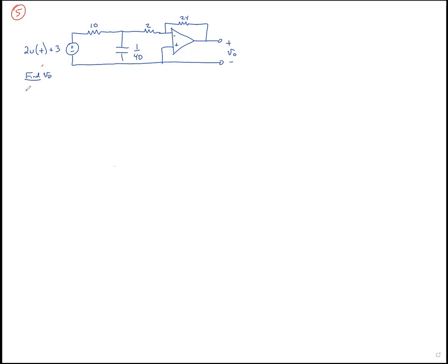So your first step, predictably, is the same as your first step in any first order circuit. Take a look at it and see if it indeed is a first order circuit. It is. There's just one capacitor in it. Is it switched DC? It is. For time less than 0, it's being driven by one voltage. For time greater than 0, it's being driven by a different DC voltage. So you can use the first order plug and chug technique.